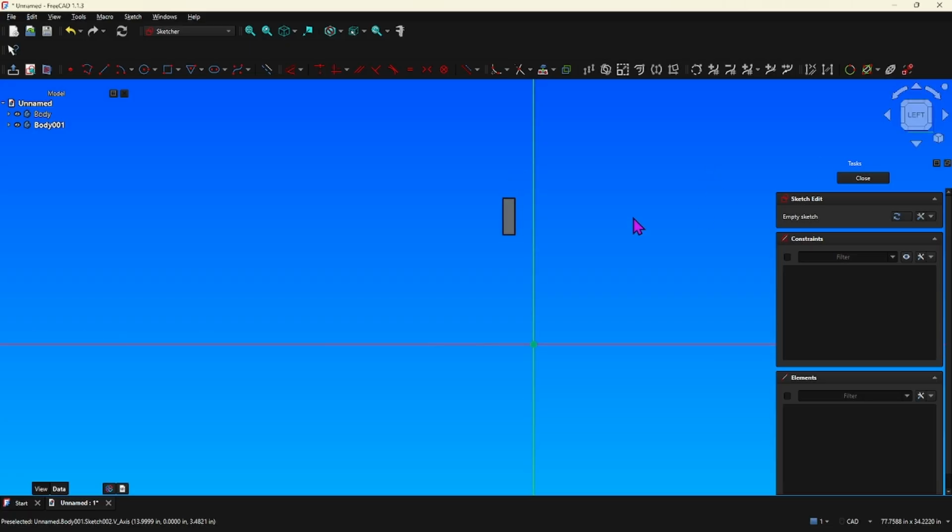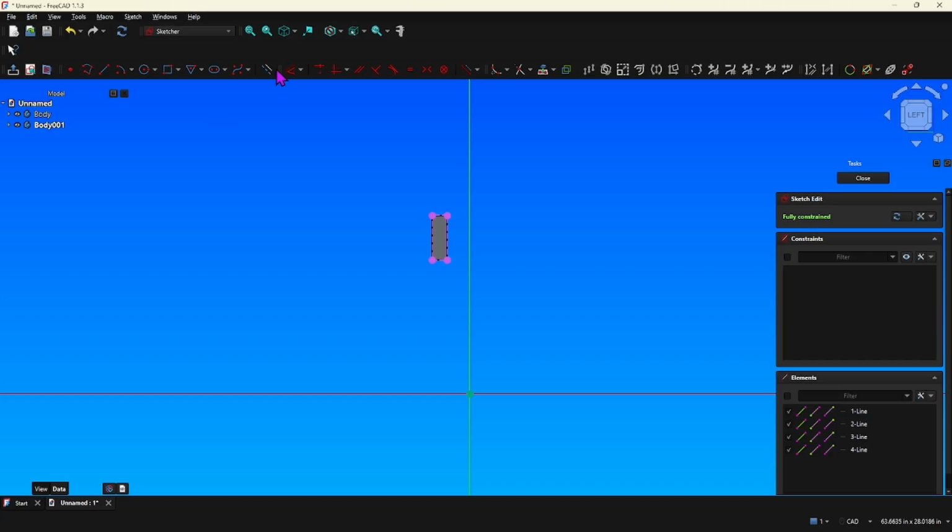So put it on the left. Here, we will need the external projection, select that, just select that face, and then it gives us geometry that we can reference to. I'm going to put this back into not construction mode. All right, so what did he do from here? I believe he came in a 1/4 inch all the way around on all sides. So let me try that.